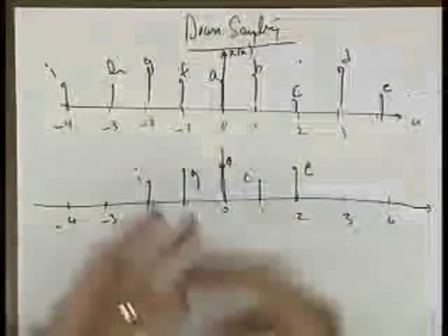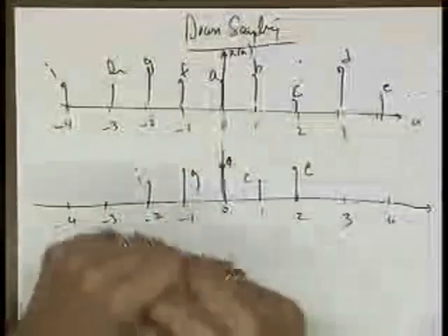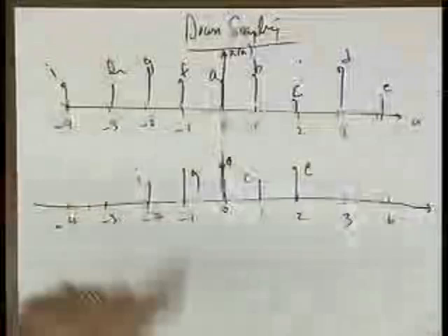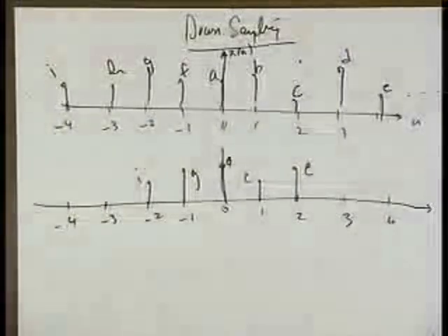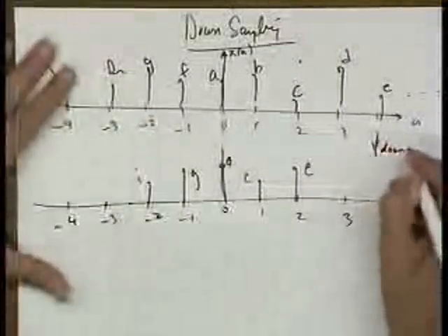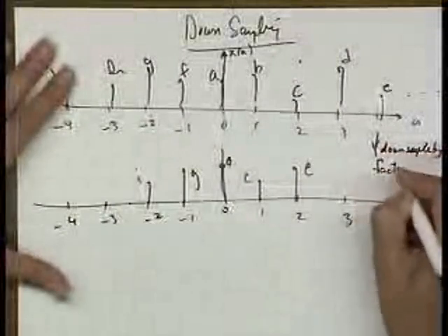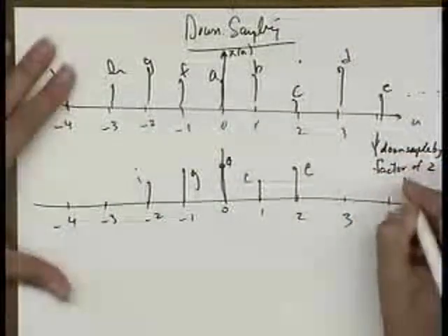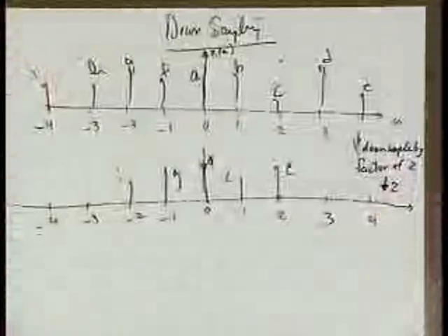That means I've downsampled by a factor of 2. I could downsample by a factor of 3, which means that I keep 1, throw away 2, keep 1, throw away 2, keep on doing that, right? So this is downsample by a factor of 2. And sometimes they denote that with an arrow and a 2. That's sort of the mark for it.